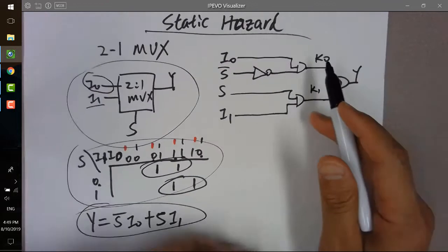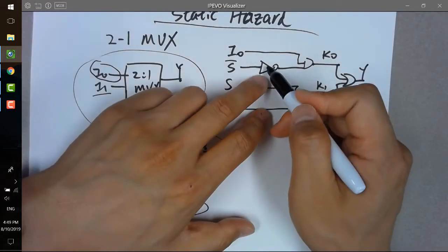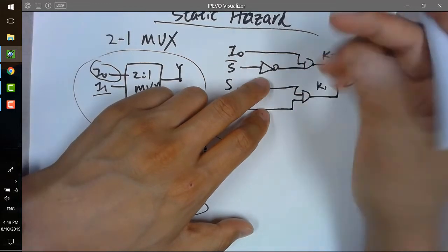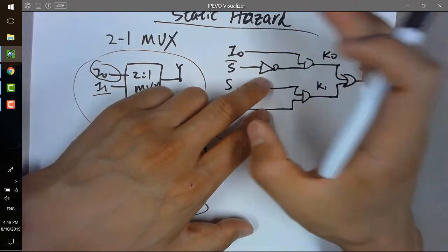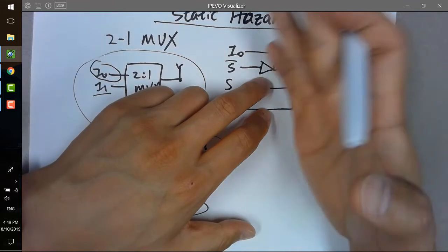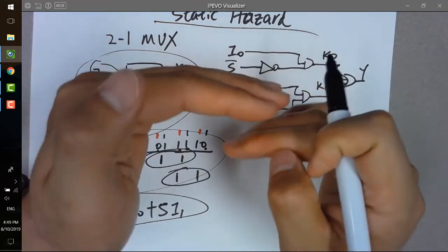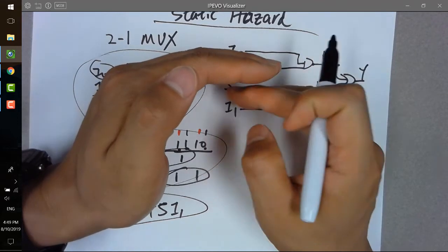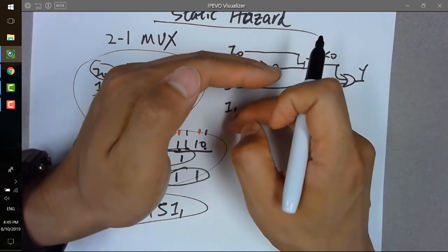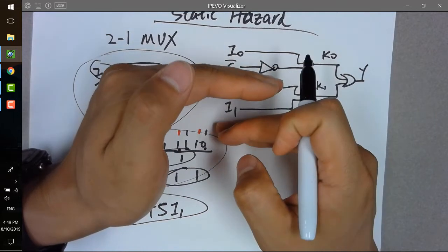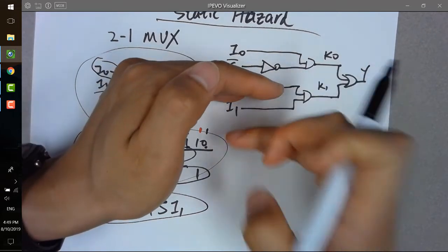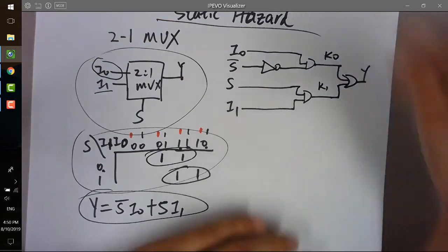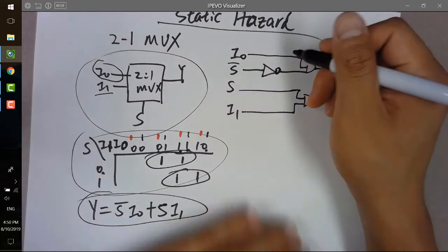And because of the natural property of the logic gates, they have parasitic capacitors. Actually, we didn't cover that because it's a digital class. All these gates have an oxide layer in the NMOS or PMOS. That's why you have a dielectric material introduced between two metal plates, like the gate, oxide, and the silicon semiconductor. So you get a capacitor. But when you have a capacitor, you get a delay in time.